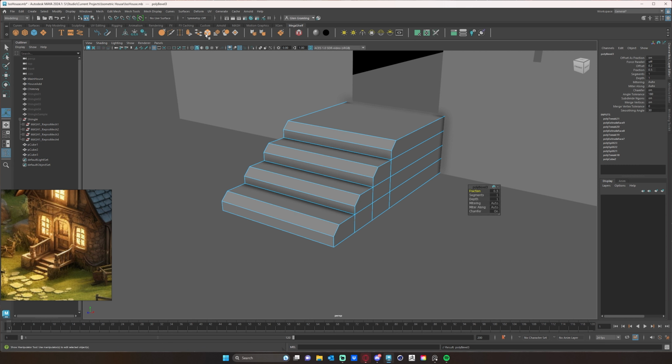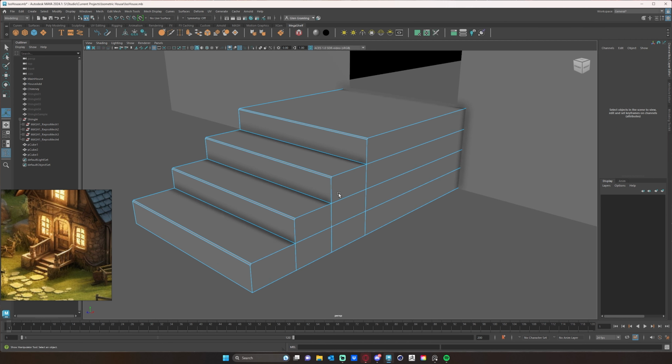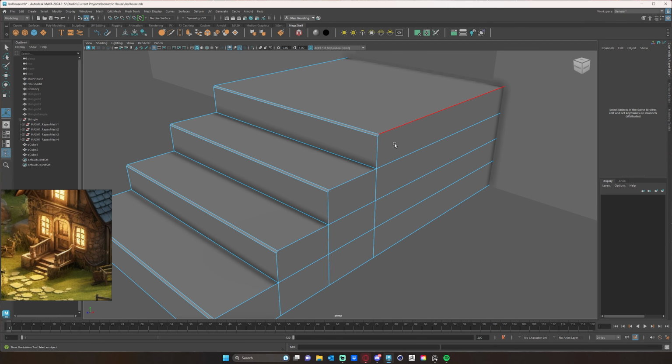So if I just do a bevel, and again, just a very slight bevel, and you can also type in some numbers. So if I think 0.1 is still a little bit much, I can come in here and just say 0.05, right? And that will give me that little bevel. Now, what happened when we did that was it makes this face an n-gon. So this has more than 4 sides on it now. So we have 1, there's a side over here, 2, 3, 4, 5, more than 4 sides. So we need to make this to where it's not an n-gon anymore.